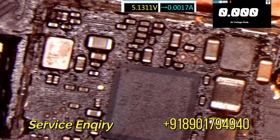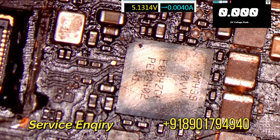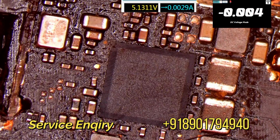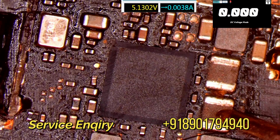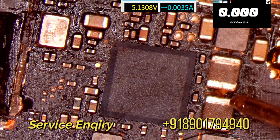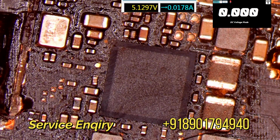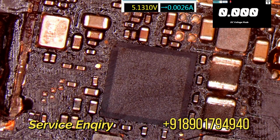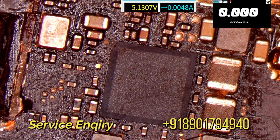Now look at this, PM439. Now clearly this phone had a minor shorting. Now let's check the buck voltages. Charging is connected already. This buck has no voltage, and this one also has no voltage. So what's happened? The VPH does not generate the buck voltages. Why? Because the power IC input requirement is VPH or VSYS, but the input requirement is not fulfilled properly.